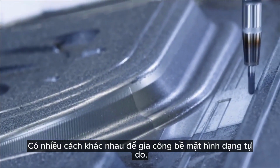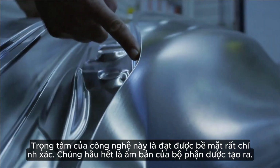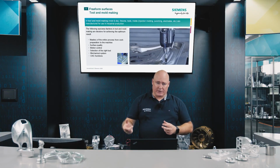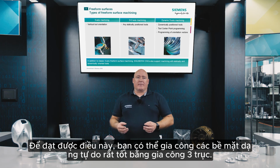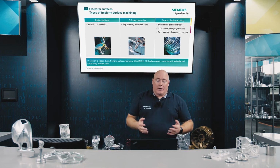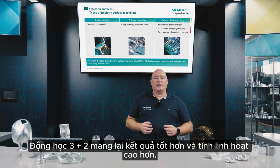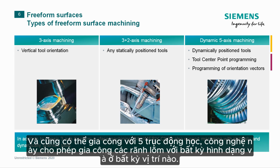There are various ways of producing free-form surfaces. The focus of this technology is on achieving a very precise surface. They are mostly negatives of the component to be produced. To achieve this, you can produce very good free-form surfaces with 3-axis machining. "3+2" kinematics provide better results and greater flexibility. And also dynamic 5-axis machining, where undercuts can be achieved with any shape and position.